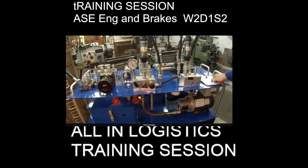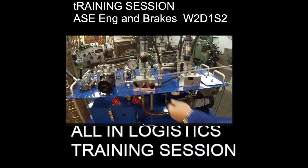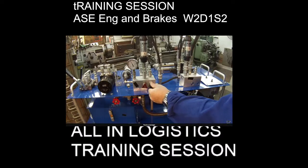So that's one of the things that's a common thing that people don't really understand. They say my pump's not pumping enough pressure. So what I want to do is go over that real quick. The only reason I'm showing that oil right here across this spring inside this relief valve is this: you'll see if I move this relief valve in and out, the pressure goes up or down based on the resistance to that oil that I'm pushing across that orifice right there.